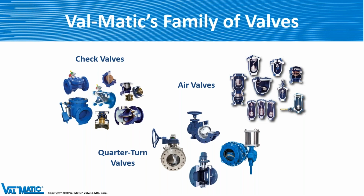Then we're going to look at this valve here in the middle, which is our surge buster. Basically, that's the swing flex with a spring in it, to get it to close very quickly, because the last thing you need is water hammer in your system. The valves over here are our inline check valves. Then we have our tilting disc check valve.